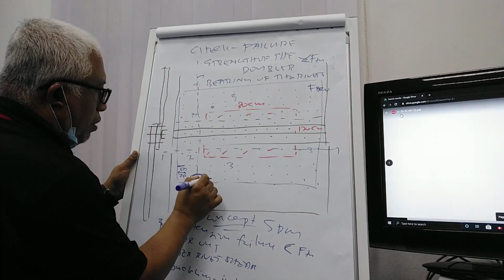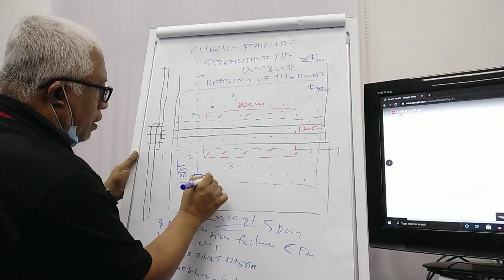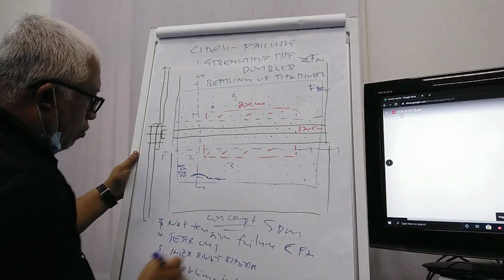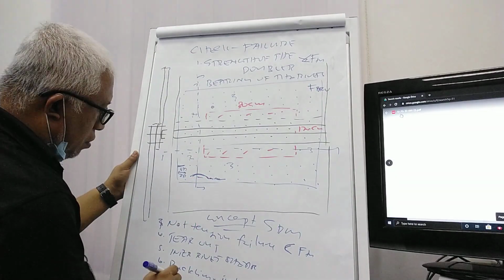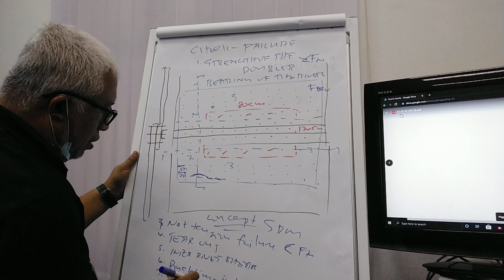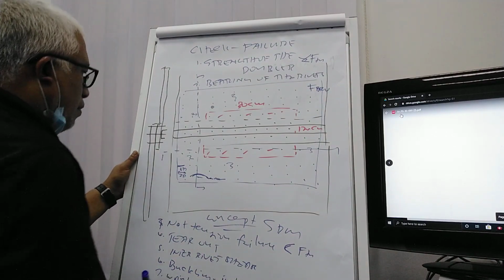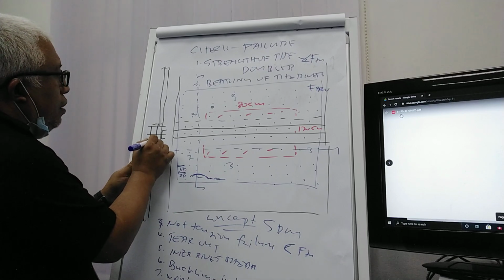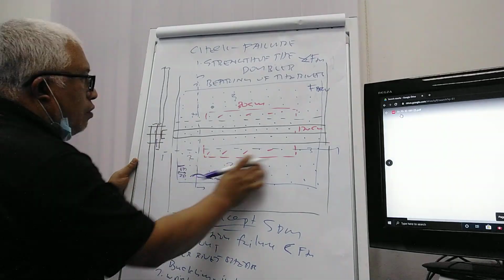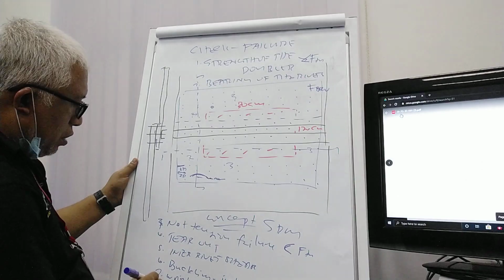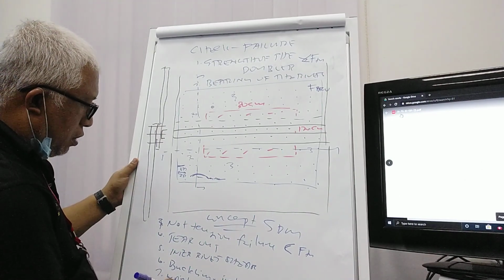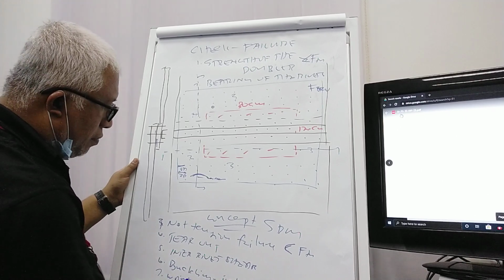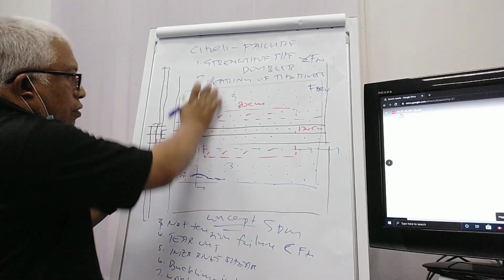Buckling is a global failure. Wrinkle. So between the rivets could be wrinkle. So wrinkling. Then the last one you check is the shear. The rivets here, the fasteners, the rivets which are holding those double plates. So we check the shear of rivet. So this is all the failure modes.